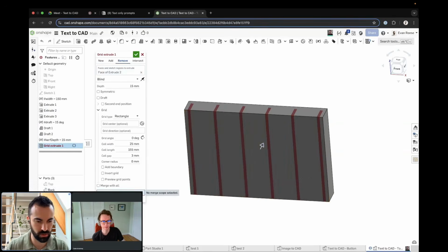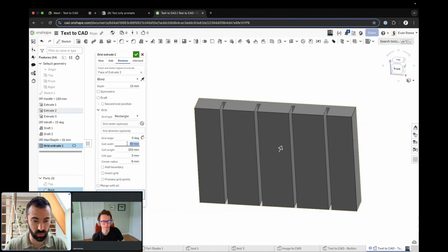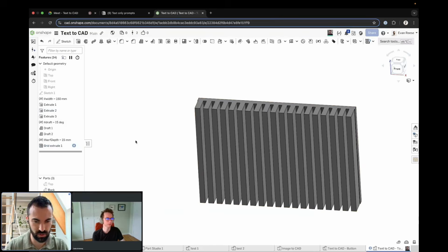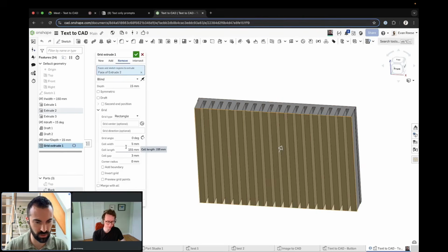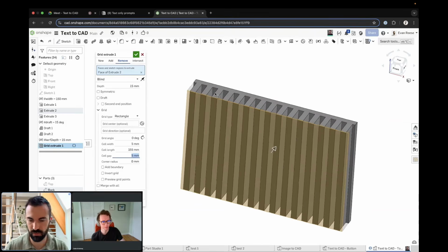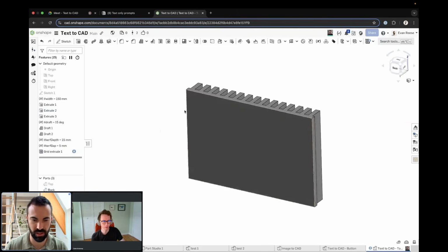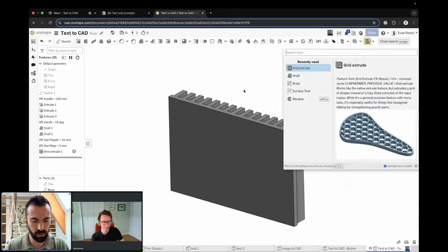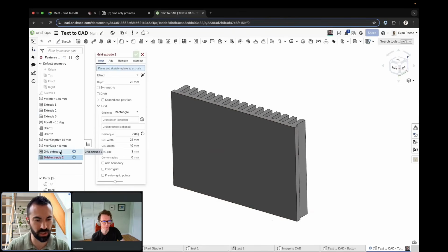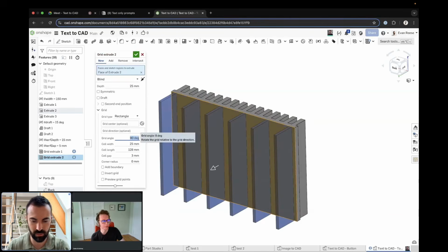Okay, and now I'll just go ahead and do this as our merge scope. The cell width needs to be 5 millimeters, and the cell gap is also 5 millimeters. So there's our front kerf, and I'm just going to go ahead and variabilize that as well, making up words here. All right, Onshape, if you're listening, I want to copy and paste this feature and just put it on the back and change a few things, but now I have to rebuild it. So I hope that you will do something like that for me. That would be delightful.